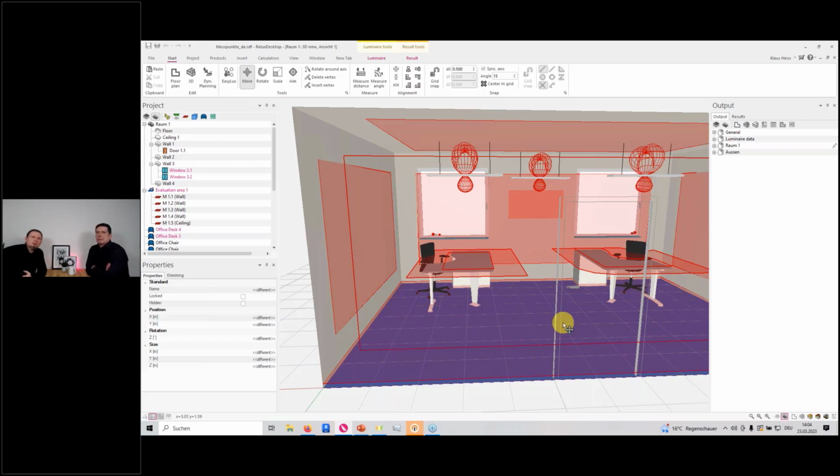You can also see that the walls and the ceilings have this half-meter bounding area. This is meant according to the standards, so that we do not need to take the complete wall. It's okay, and it's also according to standards to make a lower area because of uniformity, and also the usage of the walls is limited to a more centralized area. This is quite fine, and we have simulated it here in this room.